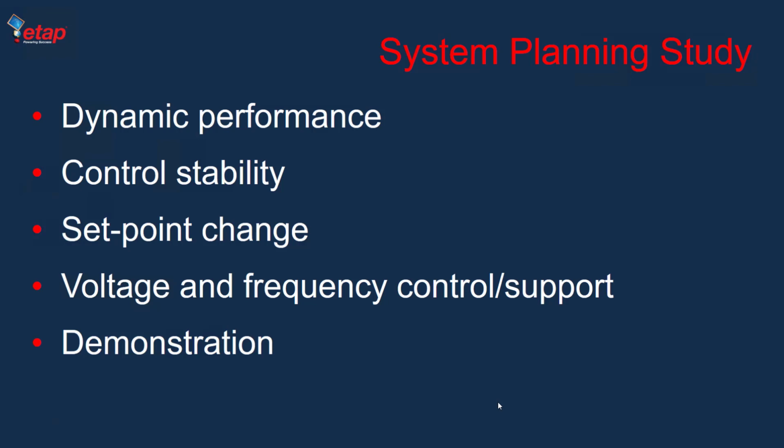There are typically two types of studies done when we are integrating distributed energy resources into the system. One study is to make sure, as a system operator or system designer, that integration of the renewables will not have unacceptable performance during system disturbances. So you want to investigate to make sure that the impact of the DERs on your system dynamic performance is acceptable. That's called a system planning study.